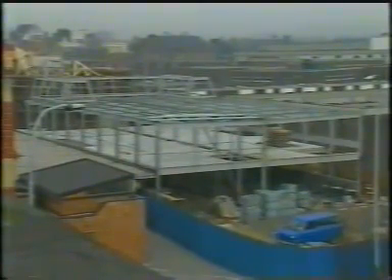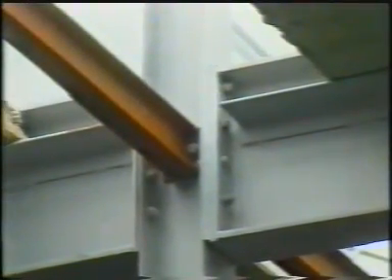Often in structural situations, continuous bracing is provided to the compression flange. For example, by a floor slab which is carried by the beam. In such cases, the beams are prevented from moving laterally, and lateral torsional instability cannot occur. Bracing is most effective when restraining the compression flange, as it is essentially the compressive action in this region which causes the instability.